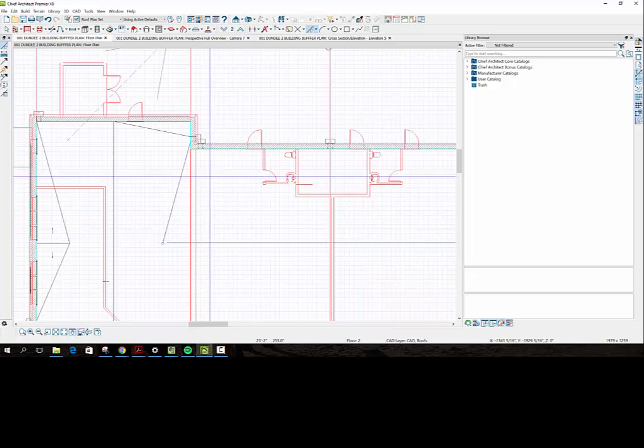Now this is going, and we're going to have to build another cricket because this is going high point this way. So we got to get it to find these downspouts. So we're going to have to find a cricket at the midpoint here. All right, which, believe it or not, that's there. Draw a line there. Draw a line there. Draw a line there. Midpoint is that guy there, so there's our midpoint between those two.